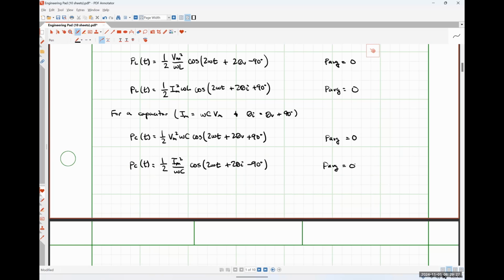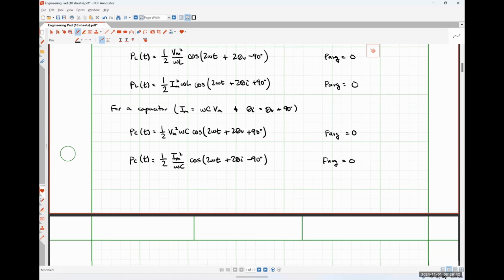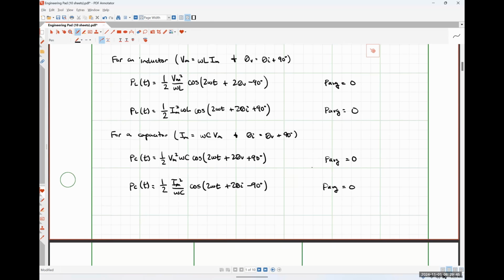All right, so before we move on from this, you're going to have in-class assignment problems to work and homework assignment problems to work where you're applying this equation. The most common mistake that I see, just to clarify things here, and this is true for any of these individual parts, so I'm just going to talk about it down here. This bit right here is an angle in radians, right? So omega times some time in seconds, so radians per second, times seconds gives us an angle in radians. We all okay with that dimensional analysis.